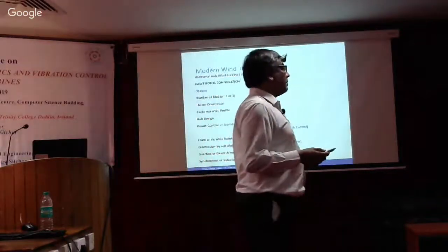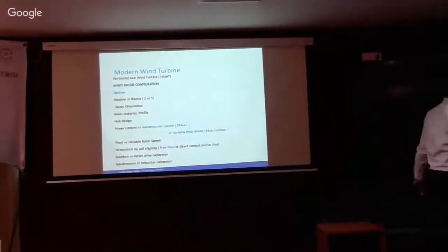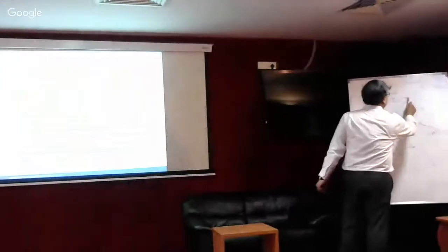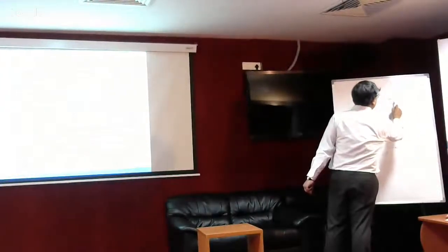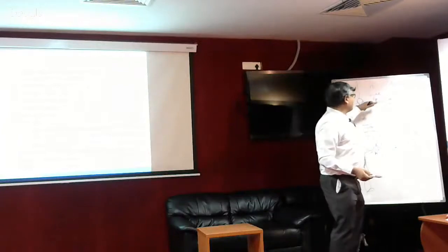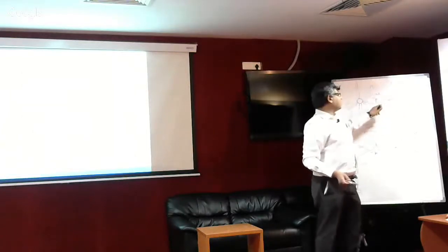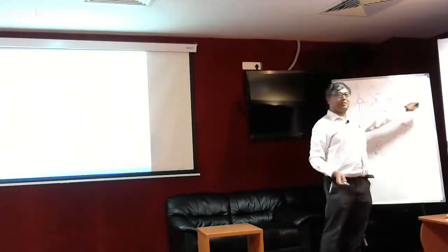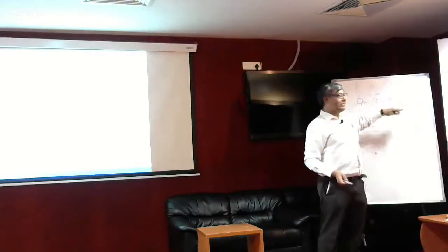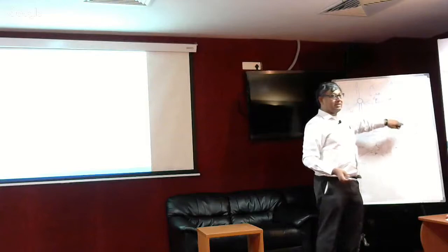But essentially, what happens is, and this is the assumption, that this flow sticks to the surface. If it does, then you can see that because of the shape, this distance is actually greater than this distance here. That means the flow at the top has to traverse a longer path compared to the flow at the bottom, assuming that there's no separation taking place. That's why this is different from this. I said this doesn't happen.